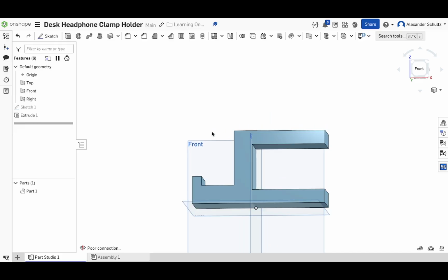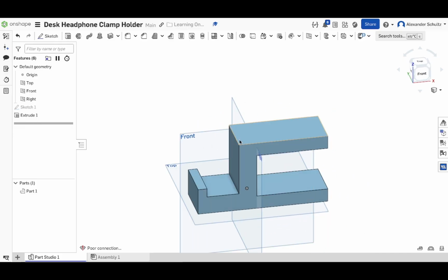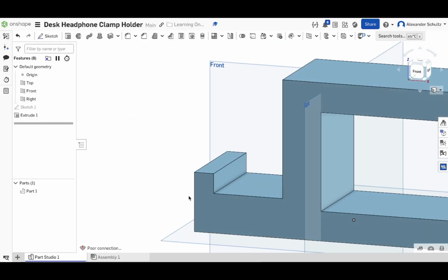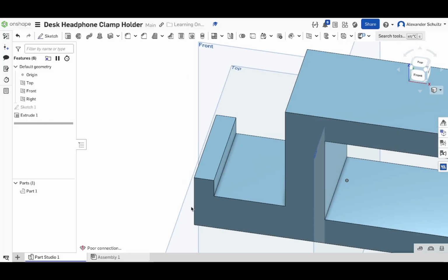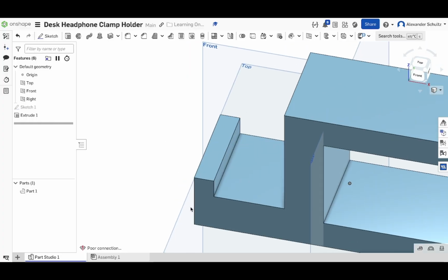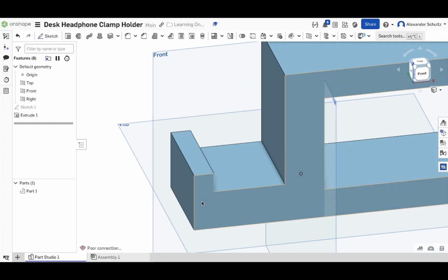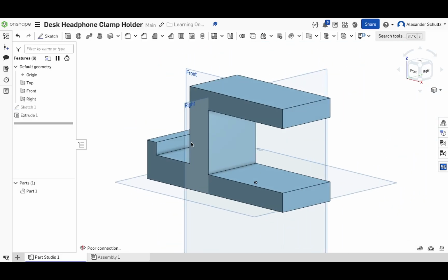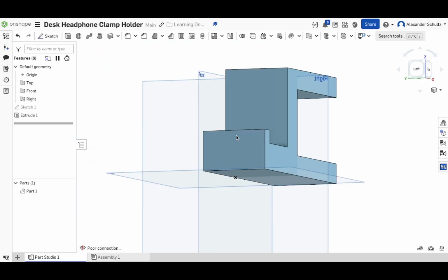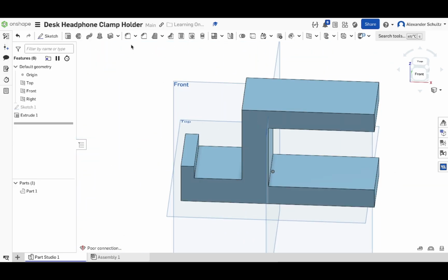So you can see these sharp corners might not be very good. You might not want sharp corners on your piece, and also sharp corners add stress to the part, and for 3D printing they are points where it would peel, because if you were to make this, you'd probably want to 3D print it. So there's this other option called fillet.